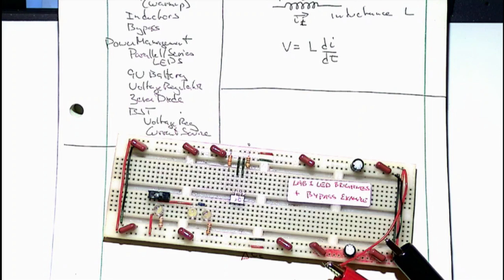So I will always insist that if you have grounds top and bottom, which I like, that you have a ground on both ends, a line on both ends connecting them up. But I do it with the 5 volt too. And once you build your final projects, I've seen people build final projects with like 12 breadboards with one little wire connecting each one. And by the time the 5 volt gets to the last one, it's like 3 volts.